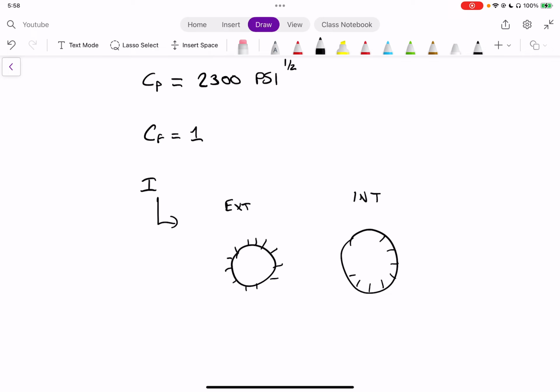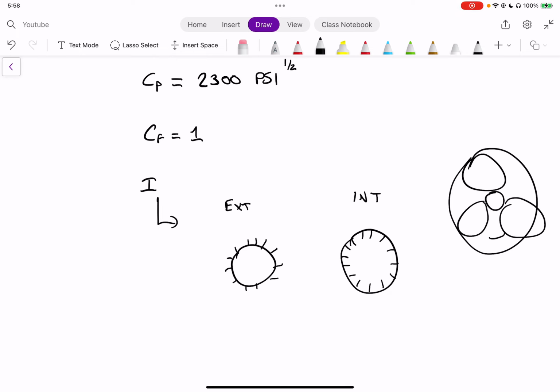Some of the times that we use internal gears are when you use gears that are facing inside with other gears that are within the circle and rotating around. An example of this is a planetary gear system where you would have, for example, 3 gears rotating around this system. This is a very rough diagram, but it explains what we have. So in this case, we do not have internal gears. We're usually always going to deal with external gears, but there are some specific cases, such as these planetary gears, where we actually have an internal gearing system.